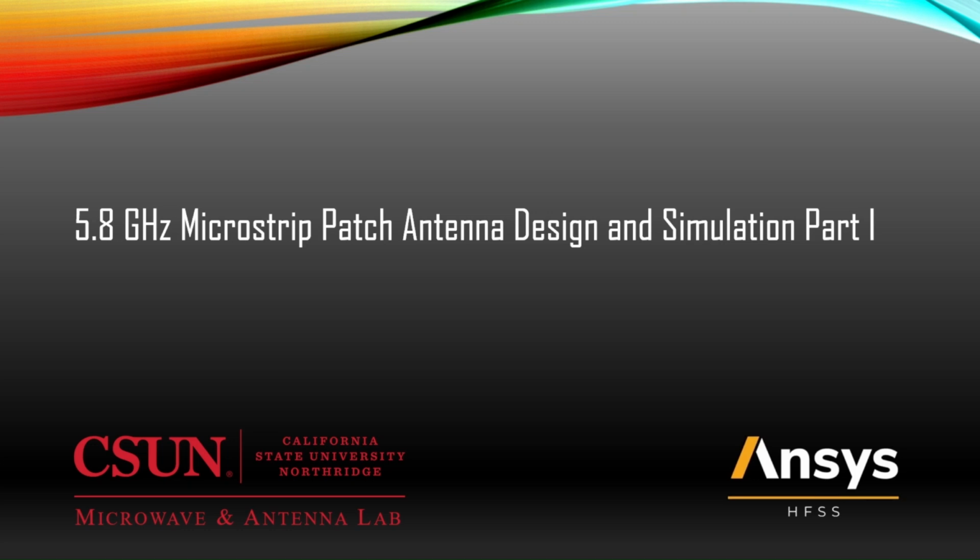Welcome. In this video, we'll be learning how to use the HFSS Antenna Toolkit to create simple antennas rapidly. We'll be creating a 5.8 GHz microstrip patch antenna with custom parameters, simulating the antenna, and then viewing and exporting the data for post-processing. Before we start this video, I'll assume you know a little bit about HFSS, such as creating projects and navigating the software. So without any further ado, let's get started.